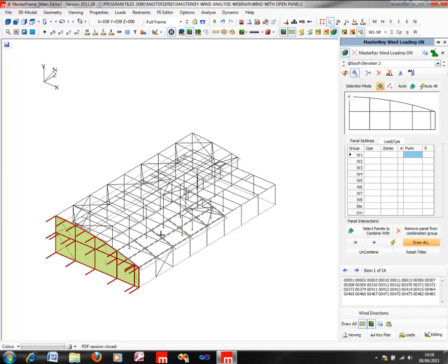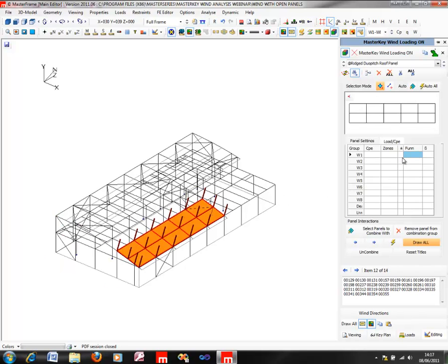Finally, to look at some of our roof surfaces here, where this plus minus setting might be relevant. Those of you familiar with the 6399 will know there are instances where, particularly for sloping surfaces of the higher angles, you have cases whereby you have both positive and negative values given in the tables of code for the coefficients of pressure. Now by default the MasterSeries is always going to go for the negative, which is the suction.